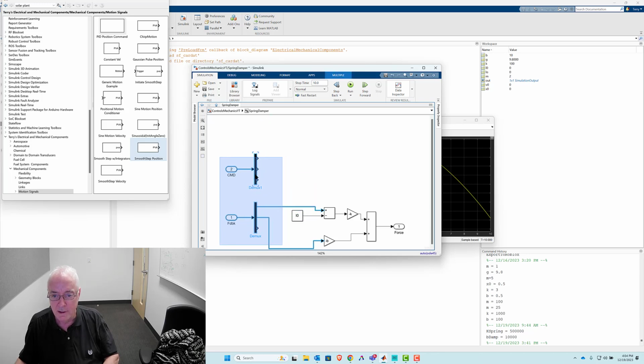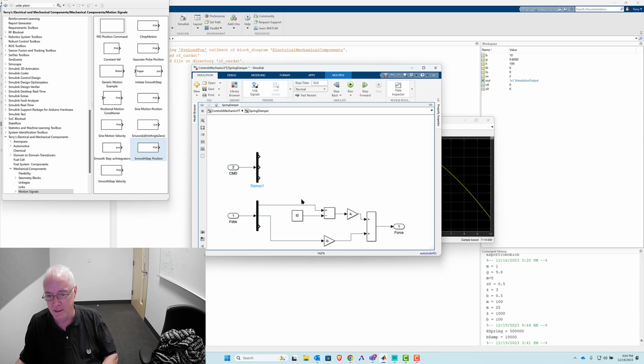And so anyways, I'm kind of asserting this idea that there's an analogy to it, that a spring damper turns out to be a PD control. And the way it works is pretty close to what we have here. I'll just say these are notational things, but they are important. And so it's no longer, I'm going to go ahead and keep K in there. Normally that'd be called something else, but we already got it defined in our data file, so I'm going to continue to keep it.